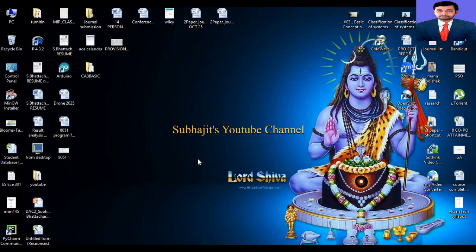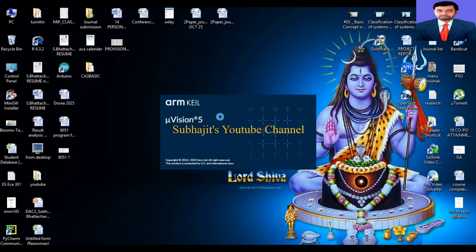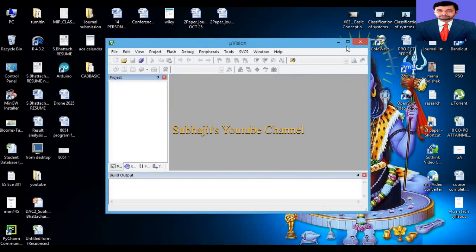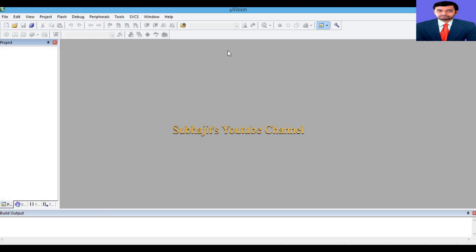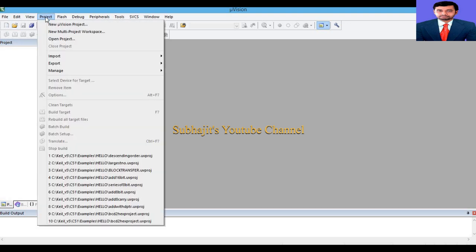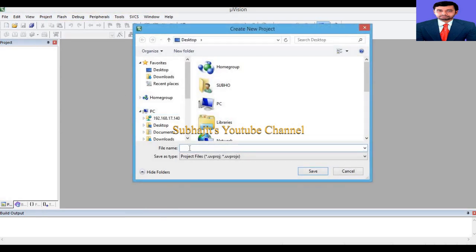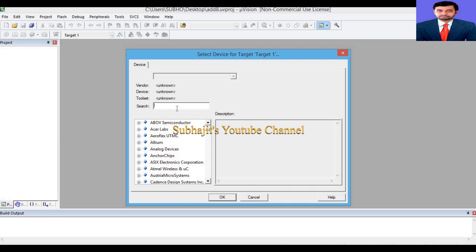Okay, now for the simulation purpose we are going to open Keil version 5 to run the program. For that purpose, first go to project, new project, give any name as you wish. I'm giving the name add 8, save it at your favorite location, then select the microcontroller series. Here I am selecting 89C51.